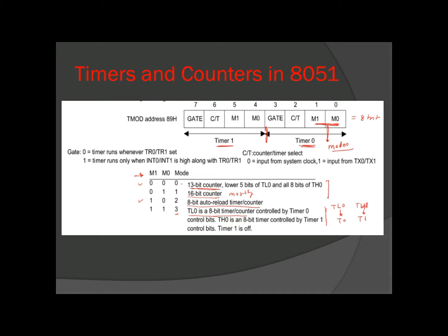In modes 0, 1 and 2, TL0 and TH0 correspond to timer 0, but in mode 3, TL0 corresponds to timer 0 and TH0 is separate.